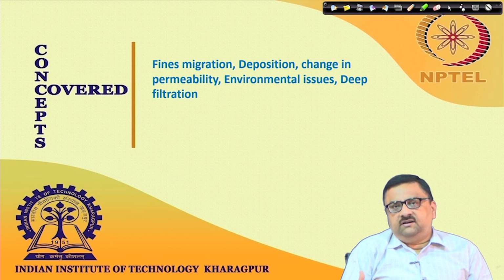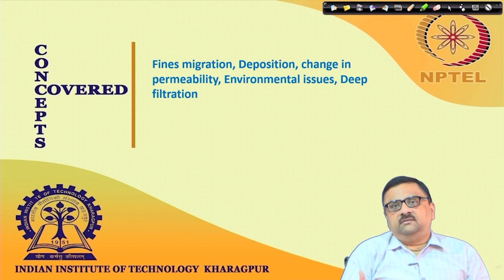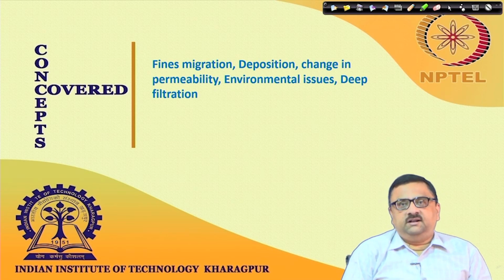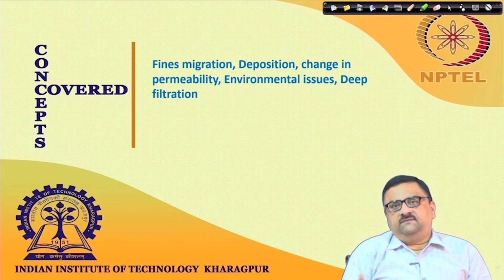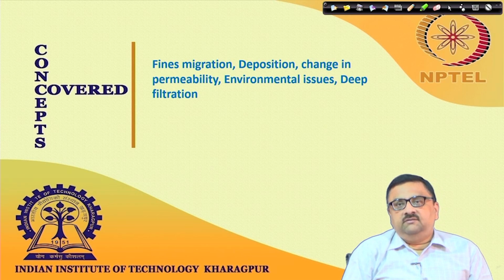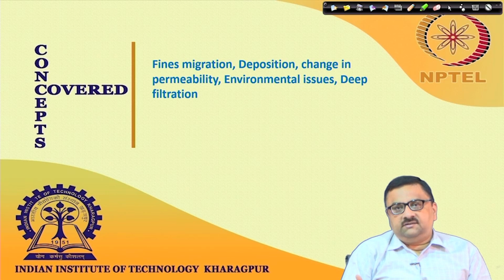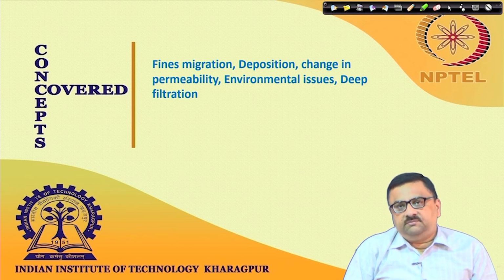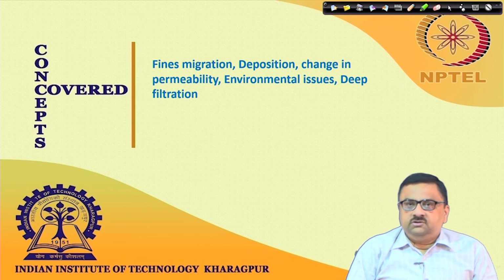We started with a deep filtration process, where we have a flow and suspended solids are plugging the pathways, and we are happy that we are producing an effluent which does not contain the suspended particles. That is what we wanted in a deep filtration process, but with time we expect the permeability will go down. Permeability going down means the pressure drop across this medium is increasing. At what rate? Because if you want to design a deep filtration process in a chemical engineering application, one must know how pressure drop will change with time or with flow. So, we are heading to that.